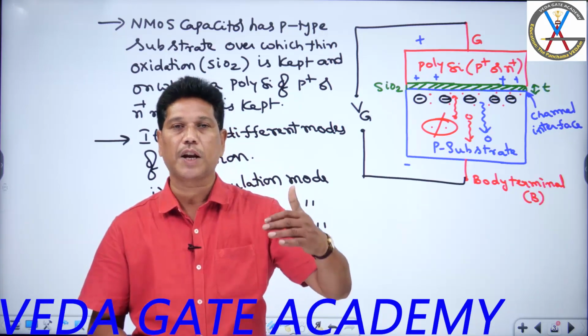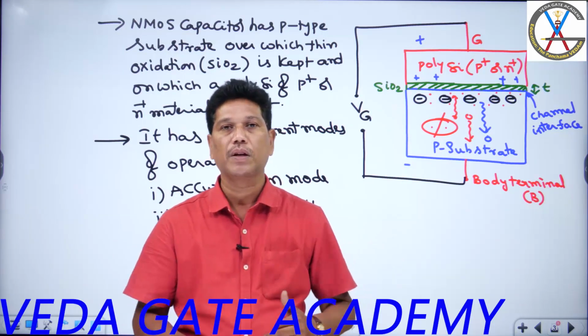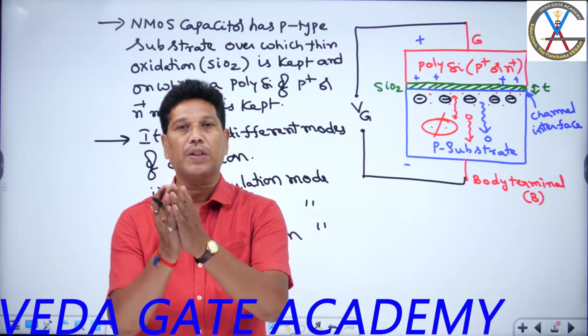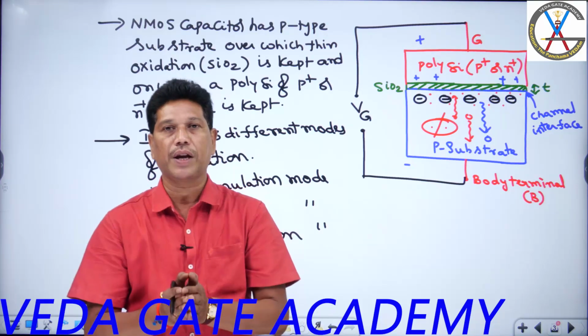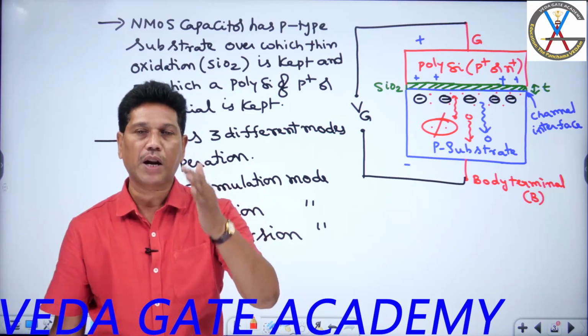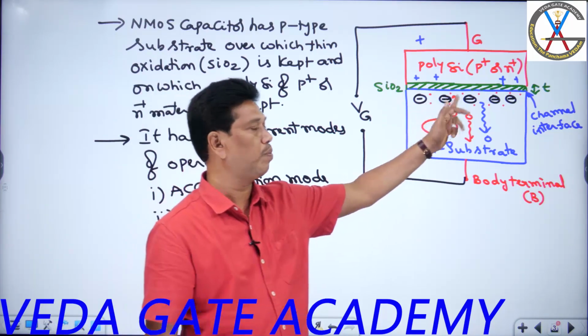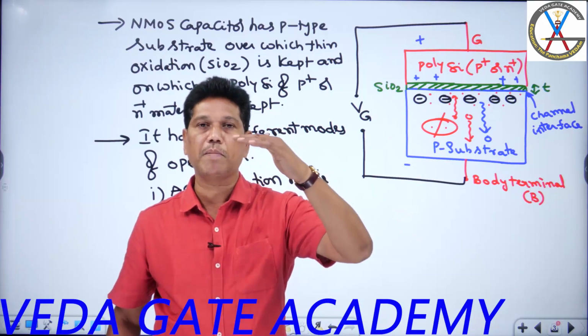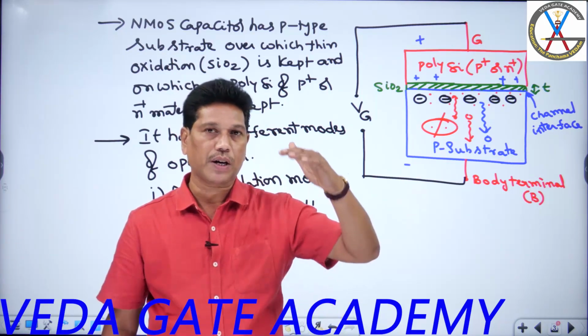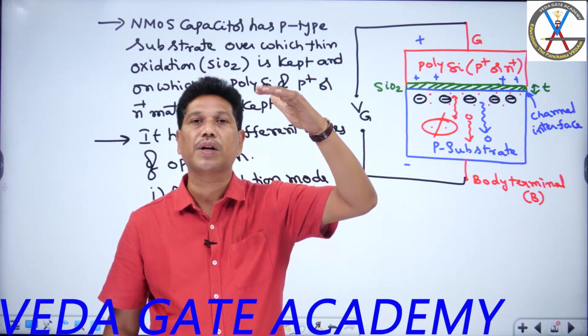The electrons move towards the interface and are accumulated at the interface, and this accumulation of electrons at the interface forms an inversion layer. So the inversion layer is the phenomenon of generation of opposite polarity charge carriers at the interface to cancel or reduce the added barrier effect. As the barrier effect reduces, the resultant capacitance increases.